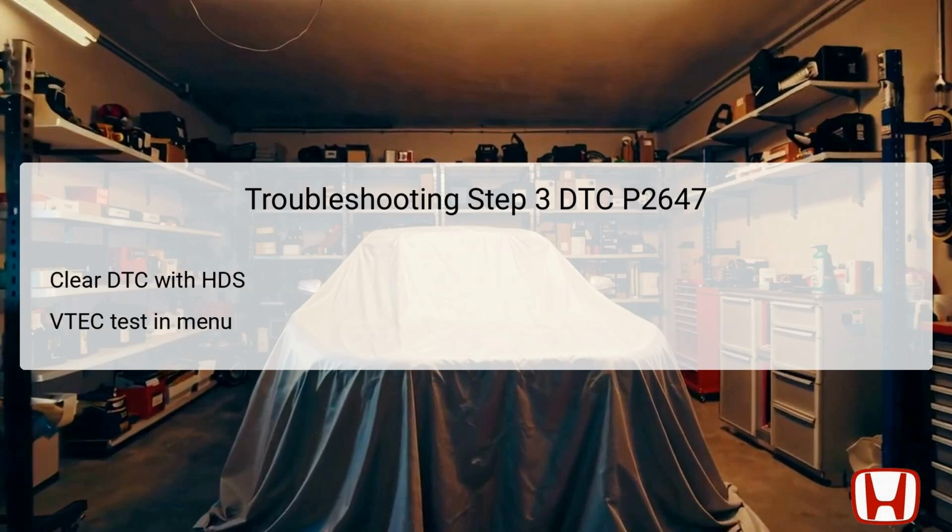In this step, utilize the Honda Diagnostic System, HDS, to clear the DTC P2647. The HDS is a sophisticated diagnostic tool designed to monitor and analyze engine system data for Honda vehicles. After clearing the DTC, conduct the VTEC test from the inspection menu within the HDS.